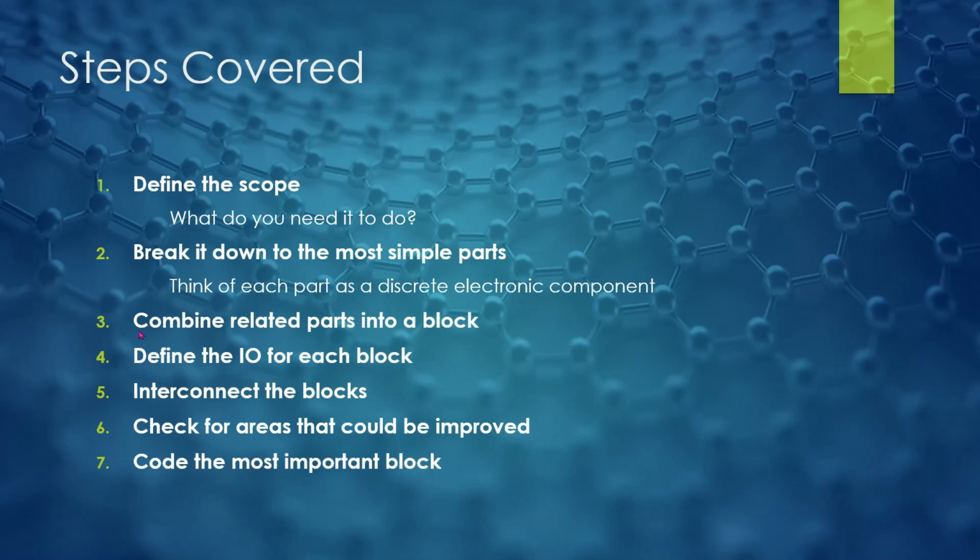So what we're going to walk through is how to create a LED matrix array. While one of my individual parts will be an LED, we'll create a block to make up 64 of them in an 8x8 matrix. And within that block, we'll then define what inputs and outputs we need. So we're going to need a clock, some serial data, obviously power, and possibly resets and things like that. We'll repeat this for each of our blocks, so we might need one for some memory, some user input. Yeah, so we'll work that out as we go through.